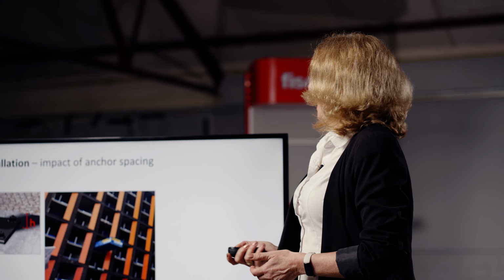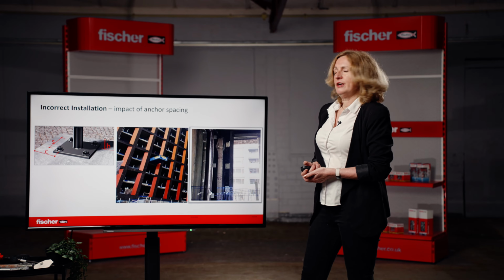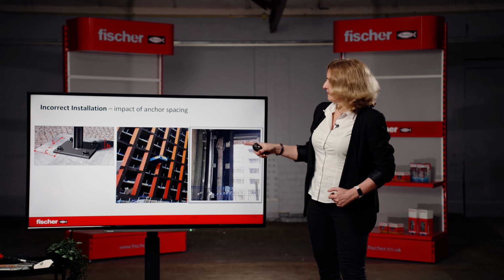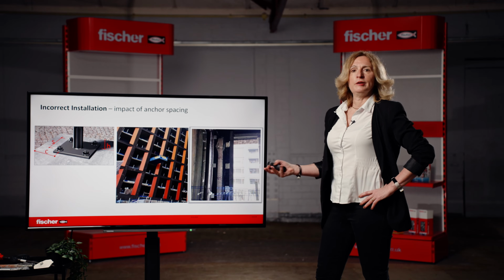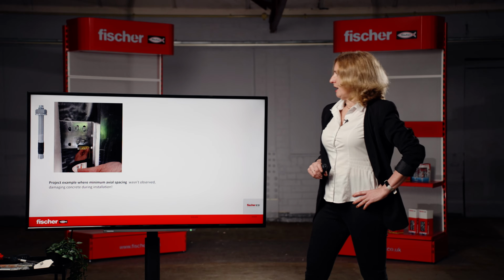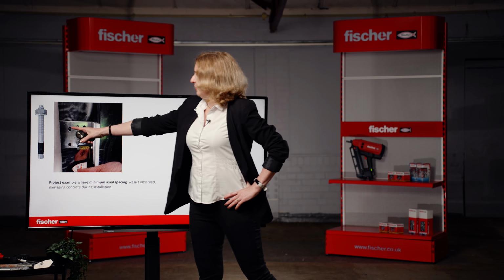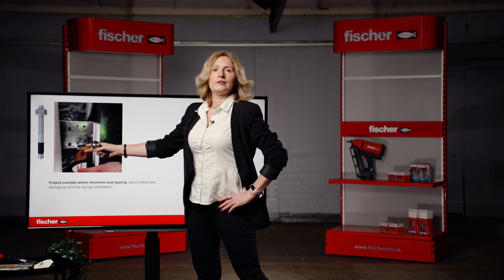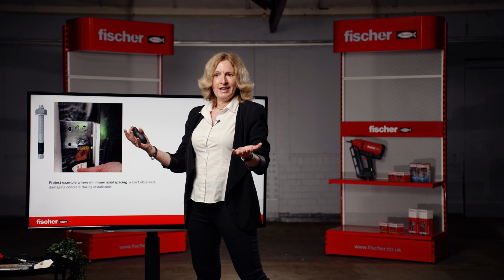On this slide, I will show you some examples from facade application. I went to site and we were observing some issues with fixing installation. Application was very simple: to install these large windows with 3 brackets on each side. Each bracket fixed with 2 fixings, simple as that. Unfortunately, in some instances, the end user decided to change the specification, and instead of installing 2 fixings here as originally designed, they installed 4 anchors,